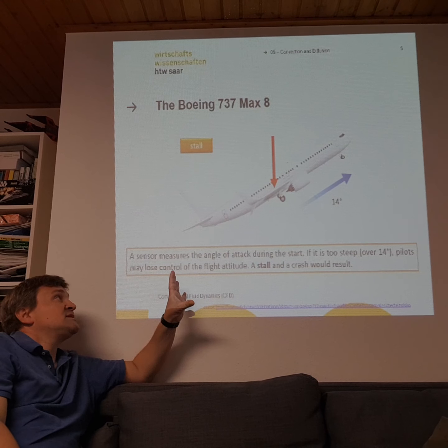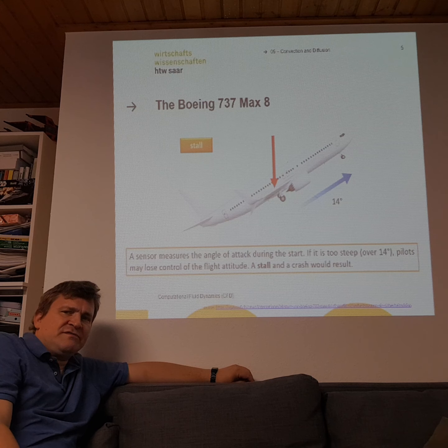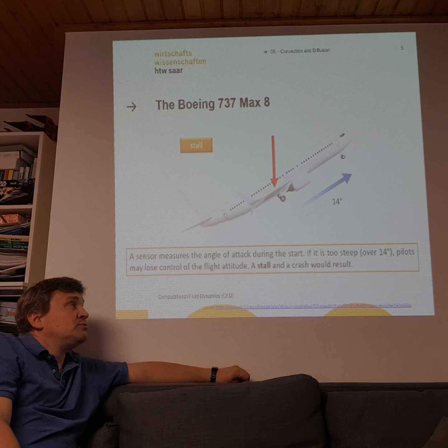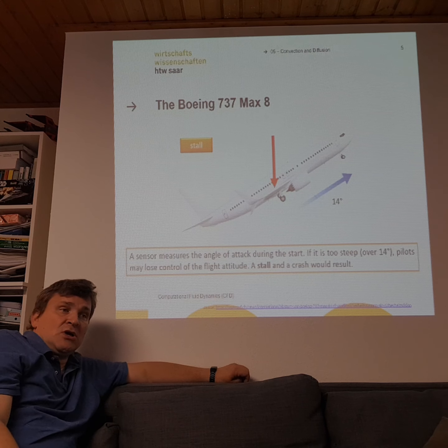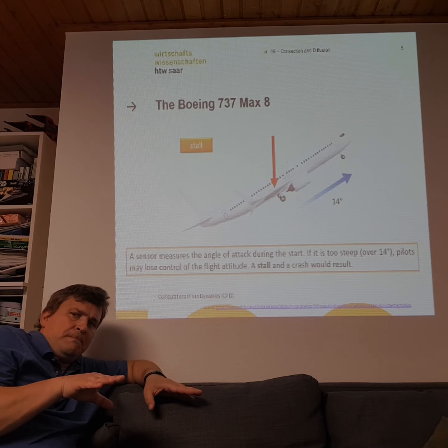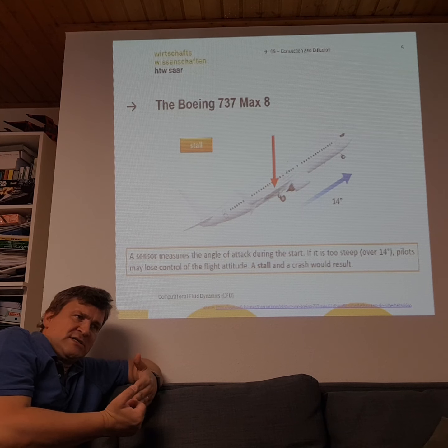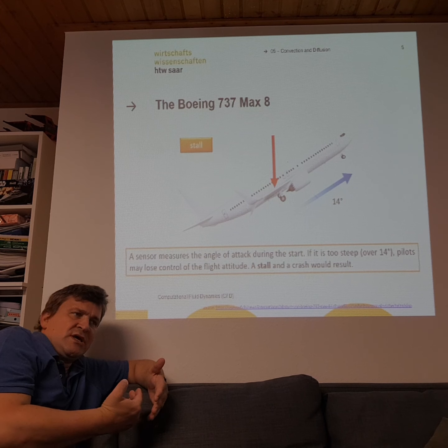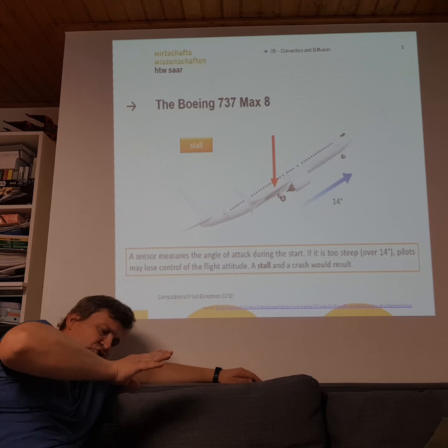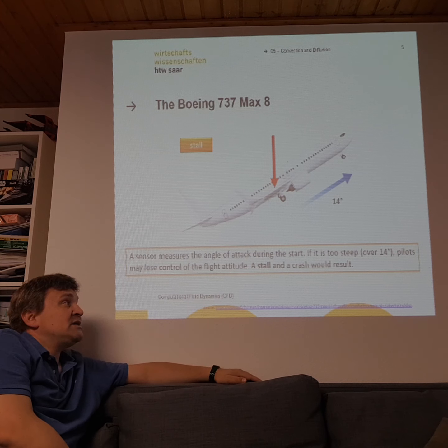So in this example they tried to build an electronic software correction function to prevent these stall effects, and they also put pressure sensors on the upside of the wing. If the pressure sensor detects stall effects, a pressure rise, the software function can act and push the nose down again to get more lift forces on the wings.